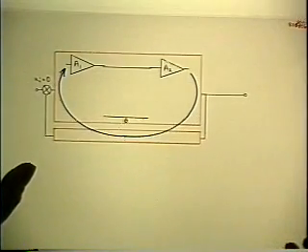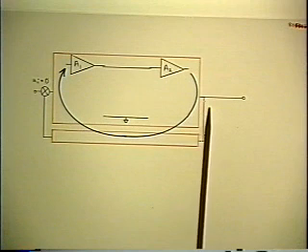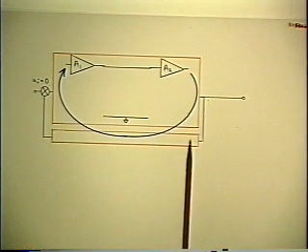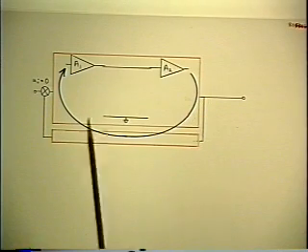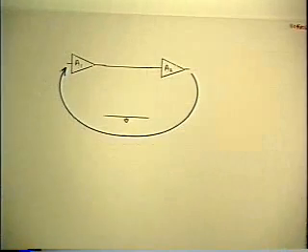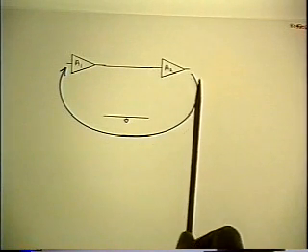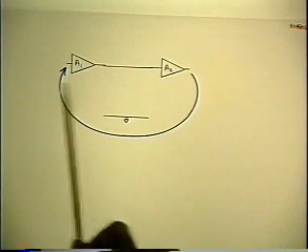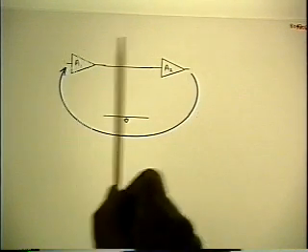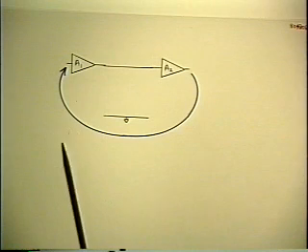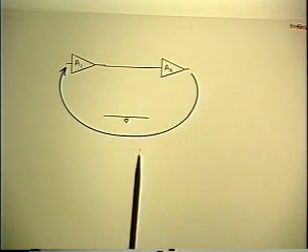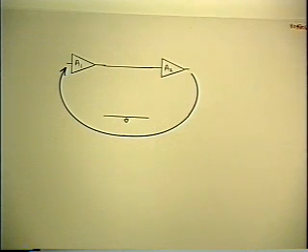Note incidentally that now that I don't need to know anything about the input or the output or the separation of the boxes, I don't even need to draw the boxes, because the only quantity of interest is the loop gain T, which is represented by this arrow connecting the output back to the input regardless of the interconnections of the feedback path. This is all we need to identify the loop whose gain we're trying to calculate.